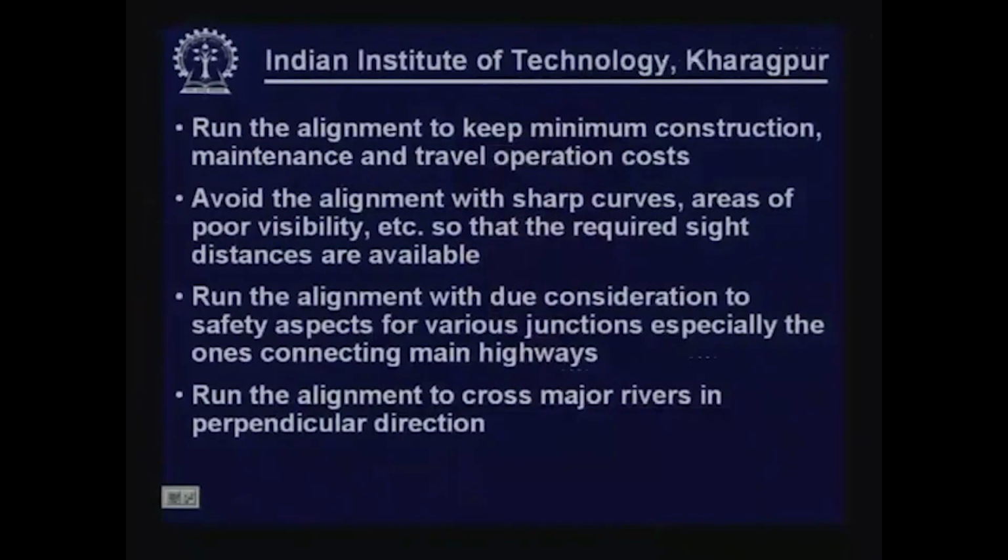Run the alignment to cross major rivers in a perpendicular direction. Of course, for minor streams it may not be a major problem, but when you have big rivers or major rivers, try to cross the rivers as far as possible in a perpendicular direction.